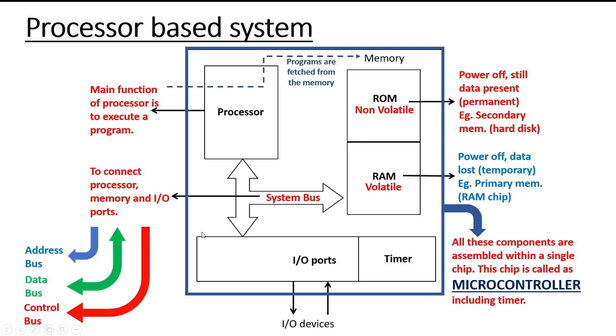So timer. In a hardware timer there is a separate component which counts on behalf of the processor, and when that count is complete it just gives a signal to the microprocessor. Meanwhile the microprocessor is doing its job. So what's the use of having a timer in a microprocessor based system? Which type of timer should we have? Should we have a hardware timer or a software timer, or in what way could the delay be created, using hardware or using software?